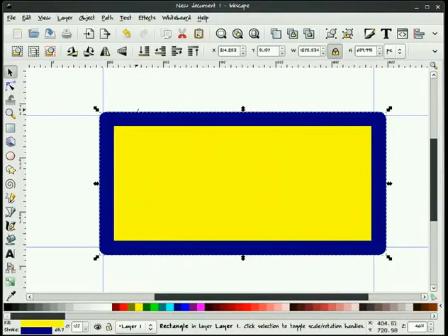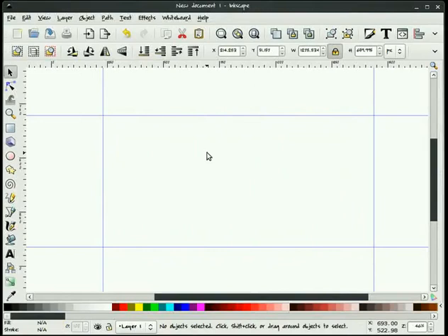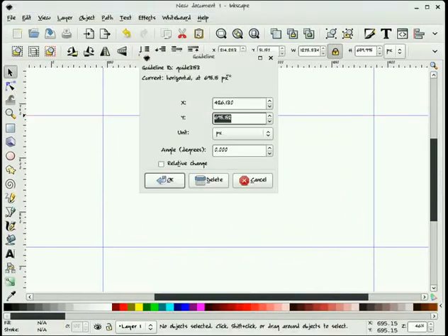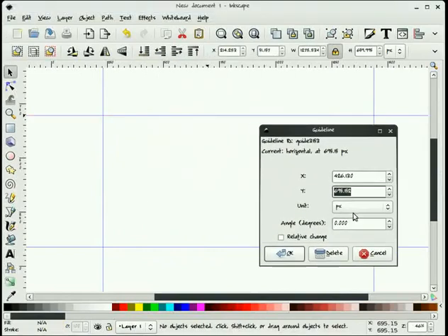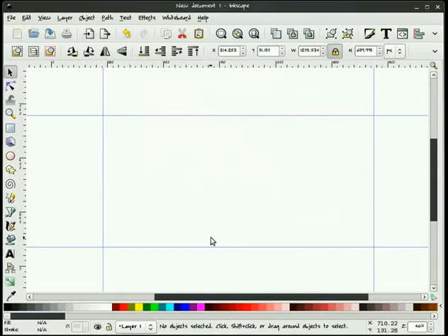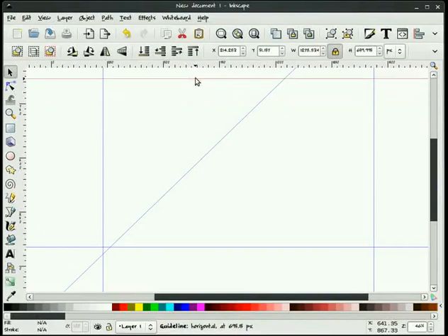It's very nice and handy. Double clicking on these guides exposes a location and units, so you can move those. You can also have angular guidelines by selecting up in the corner, and you can pull down angular guides as well. You can delete those by taking any guide, left mouse button clicking, and pushing it back into the ruler.